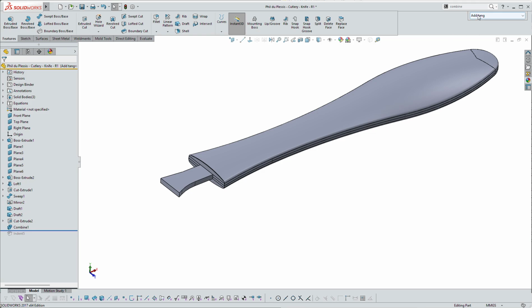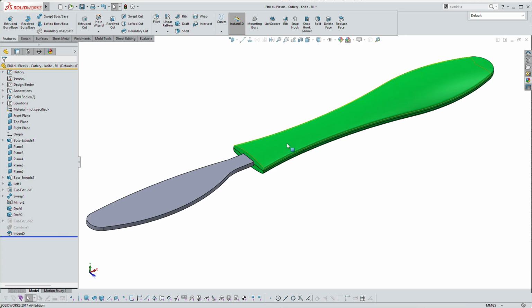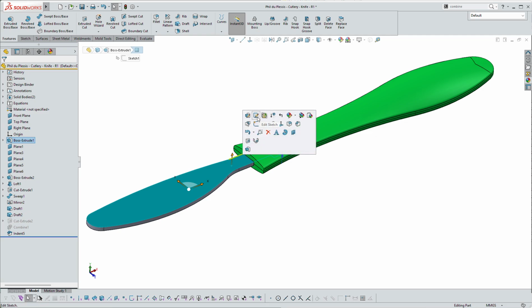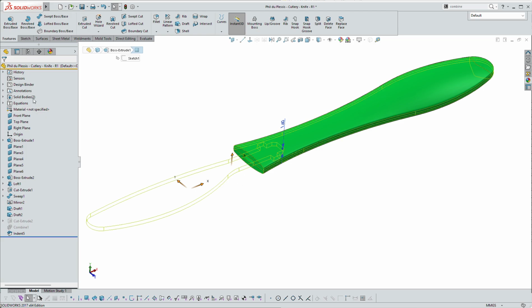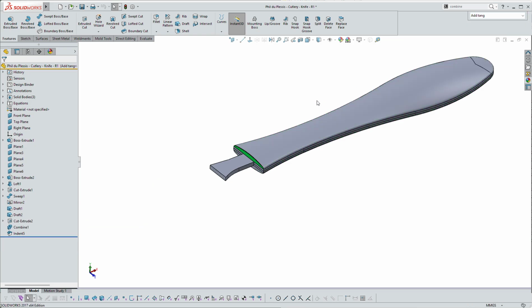What this means here is that I can now switch between configurations and have 3 different parts. So if I just roll that one forward, I've got a handle with a hole in it. Let's just hide this for a sec. So I've got a handle with a hole in it. I have a blank, right, which I can separate from the handle. And then if I go across to the other configuration, I've got the 2 together. So 3 separate parts. And that's how you do it.